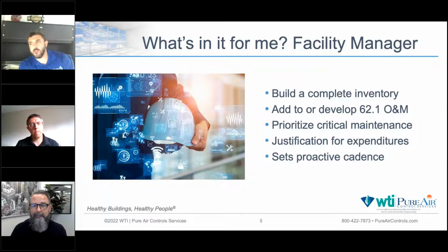Well, one thing, Troy, when you have the data of, in this case, your HVAC equipment, and you're going out there and you're being deliberate about capturing that data and doing the inspections, I think the thing that stands out, number one, is that you're going to catch issues that you can address immediately because they should be addressed immediately. I can think of a few examples. We had a hospital in the Southwest, which during one of our inspections, we found that the final filter, the HEPA filter, which served a very critical area, a patient care area in that particular hospital, was filled with mold. I mean, visibly filled with mold.